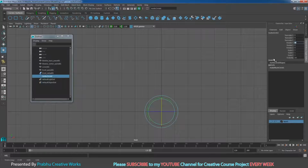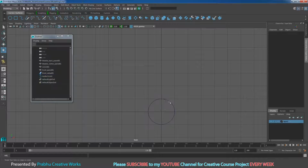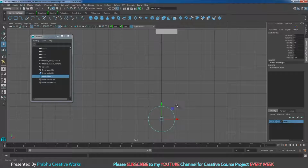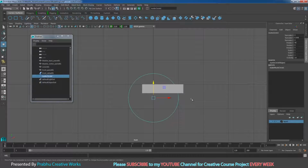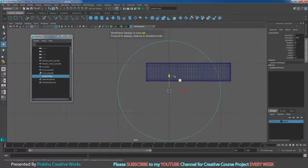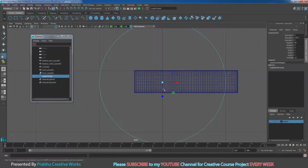So give NURBS circle section divisions to 12. I select this NURBS circle and move in Y like this. Press 4 on the keyboard to see the wireframe mode. So I will keep over here and press R on the keyboard and scale in middle like this.